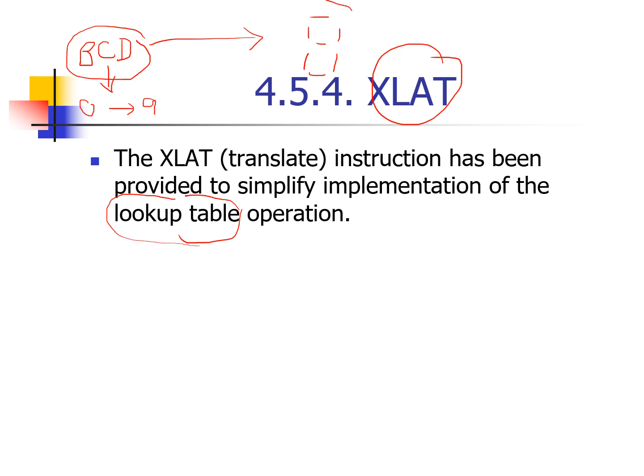You store the 10 values inside a table. We call it a lookup table. So you add here the first, second, third data, which are used to display 0, 1, 2 on your 7-segment display.